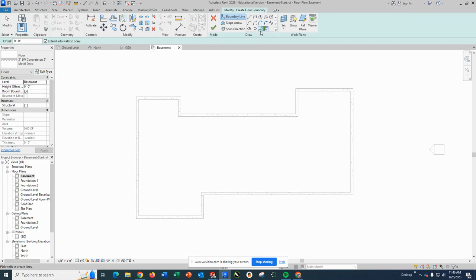But now what we're going to do is click, and right now it's going to let you pick walls, which would put it into the wall. It's not actually how it's done in a basement. The basement floor is actually poured as a slab inside the foundation walls as a floating floor. So there's dirt and all that that's prepared underneath, and then the concrete is poured on top. So what we want to actually do is use the other tool, which is pick line. And if you pick line, you can now pick the inside surfaces of your entire border.